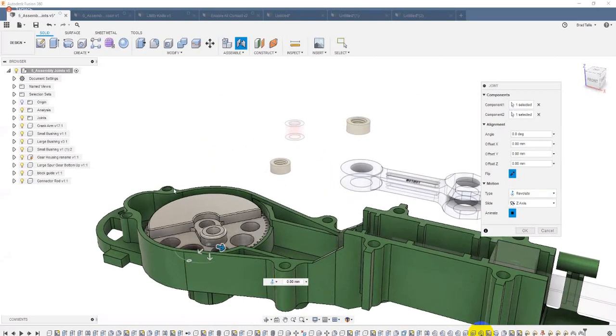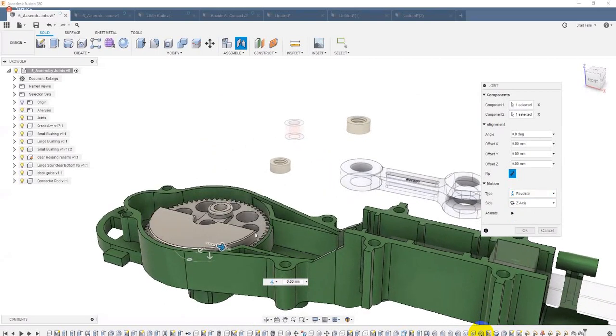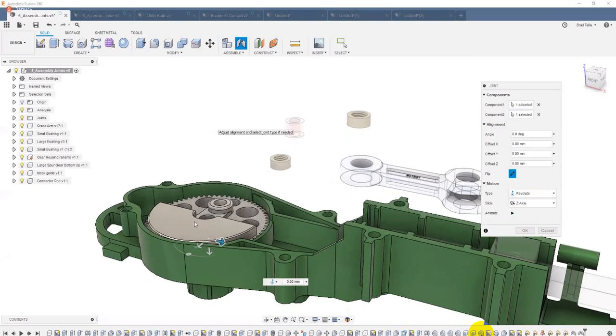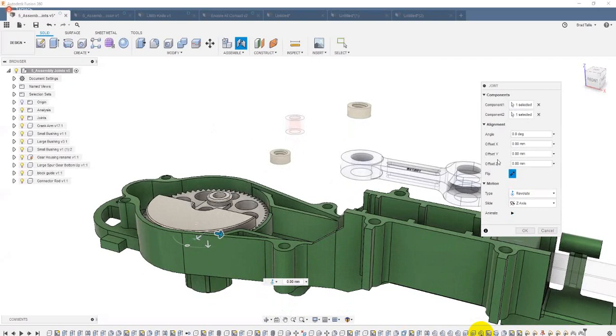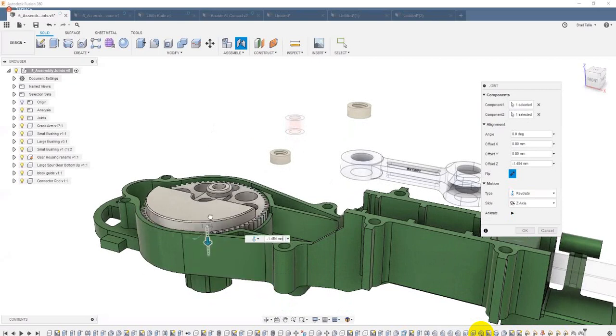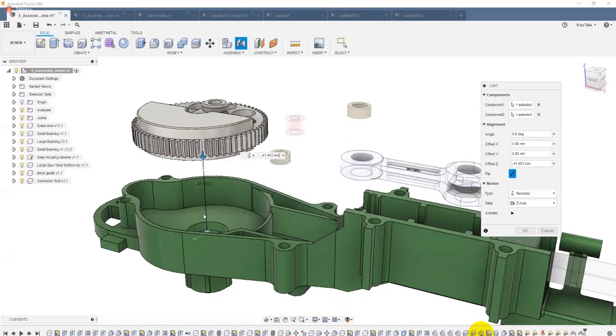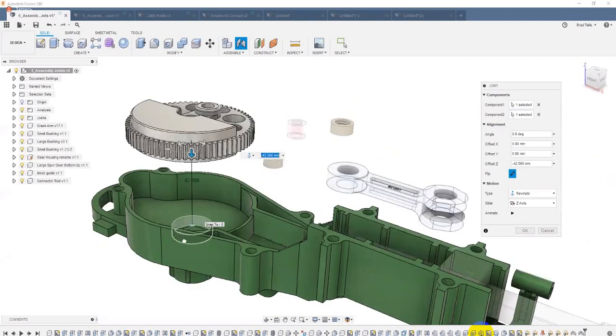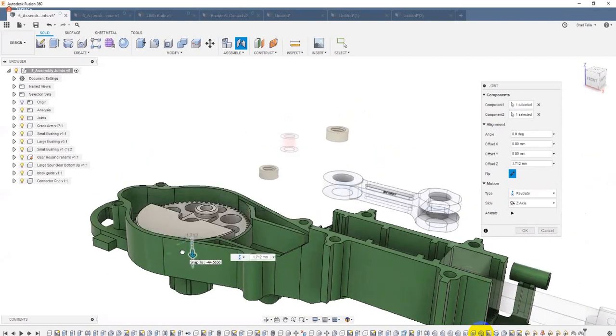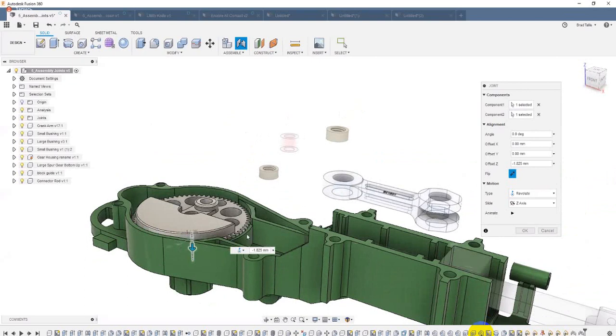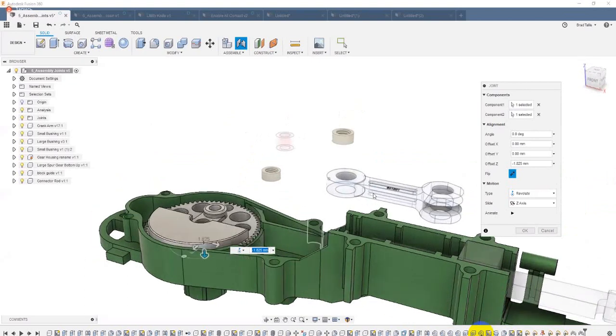So we turned off the degree of freedom for translation and we opened up the degree of freedom for revolution. You'll also notice that there are some arrows and some fields over here. So I basically twist up that bottom edge part there with the top edge. And so it did, but I can also offset it a certain distance. So, let's just say it was right there. I could bring it up a little bit, a certain distance if I wanted to. Okay, but I'm not going to.